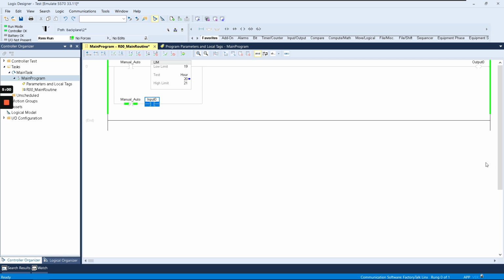And now what's missing to power on this output is to press our button or our push button, our green. Okay. Now I'm just running this drill. So Control T. This is to simulate this output, and I'm assigning a signal. And this is as if I had it powered on. And it's like it's already been shut off. So we're basically forcing our program to run the action and the activities that we tell it to do. Okay? Just so you guys get an idea.